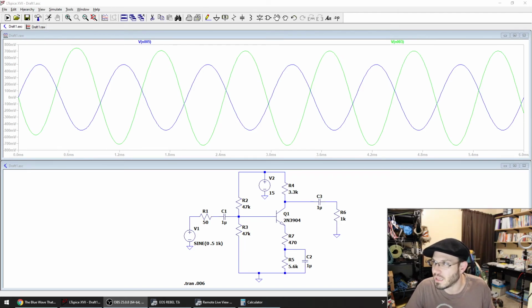And, you know, this usually in the workplace manifests itself as me just not thinking very much, connecting two things, expecting it to work, and then not asking that very fundamental question of what's the impedance of that thing that I'm connecting to, and what's the impedance of the thing that I'm connecting to the thing.